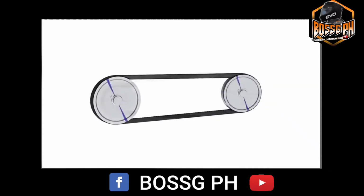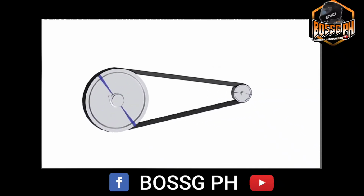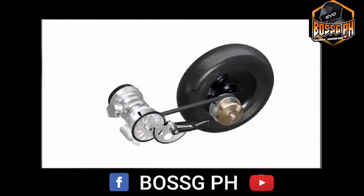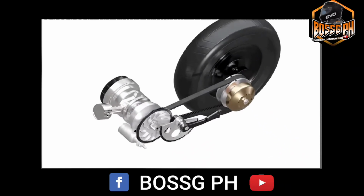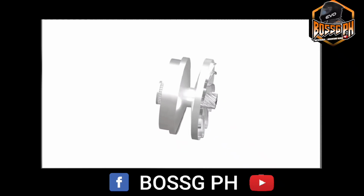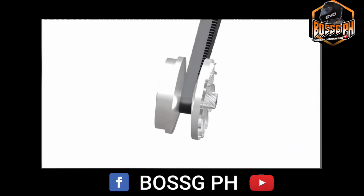It is not possible to simply change the diameters of solid pulleys as shown in this demonstration, so engineers develop certain mechanisms to obtain similar mechanical characteristics. A variator assembly is used for this purpose. Here, the pulley is made up of two conical plates. One of them is fixed to the input shaft, and the other is free to slide along its axis. A V-belt runs between these plates.